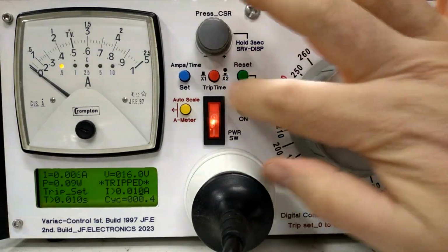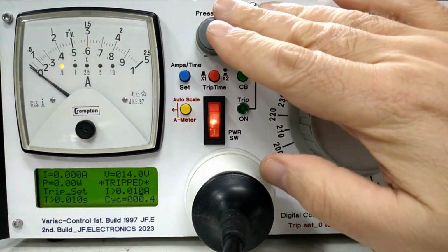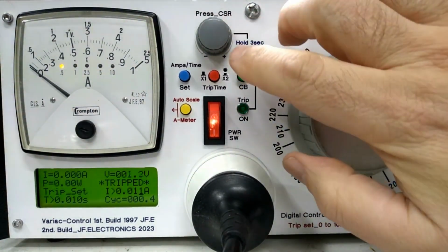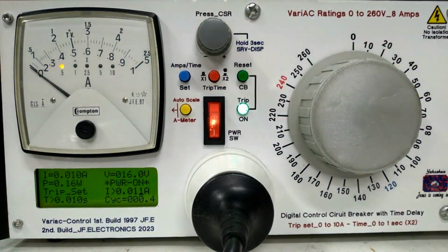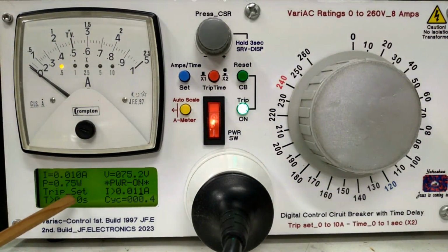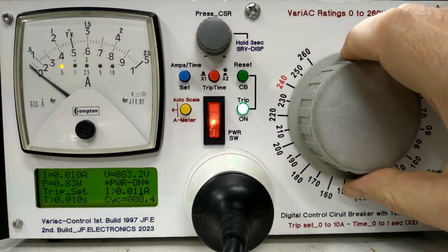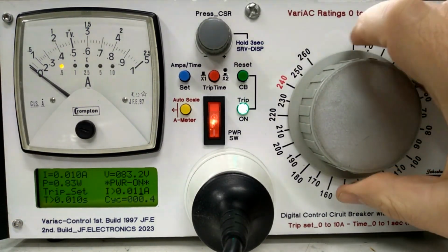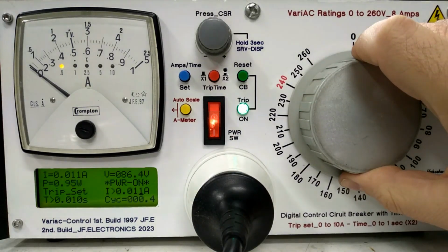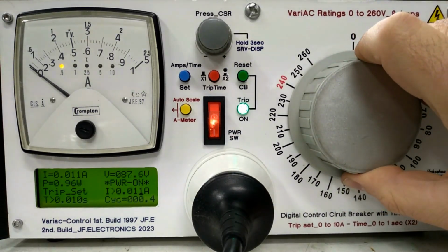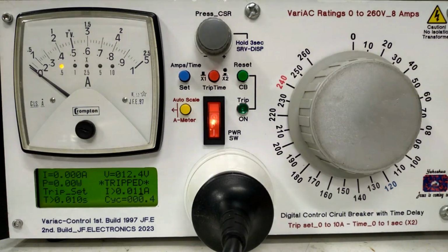Press reset again. Okay, it will trip. It's hitting the 10 now. So now I go to 11 milliamps, and when I reset it, it shouldn't trip. And there you go. It's drawing exactly 10 milliamps. So I got 1 more milliamp to go. I should trip. Turn the voltage slowly. I've hit the 11. A bit more. And it's tripped before it hit the 12.